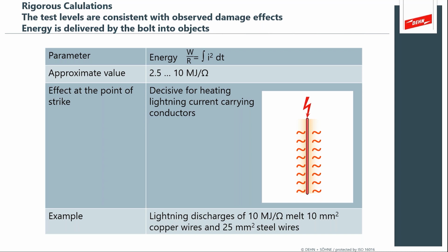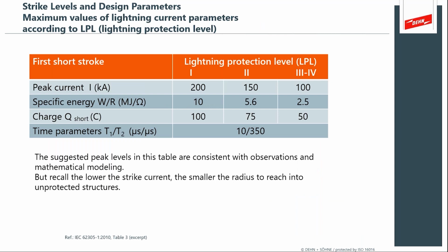And again, this is about fire prevention. So we want to make sure that our methods and our connectors all meet the standard so that you can properly protect from fire. So in the IEC 62305 set of standards, it's very useful because we have different lightning protection levels depending on your control of risk.